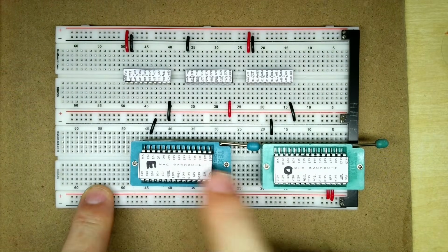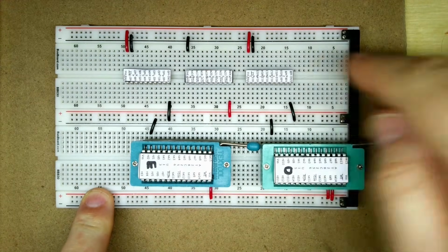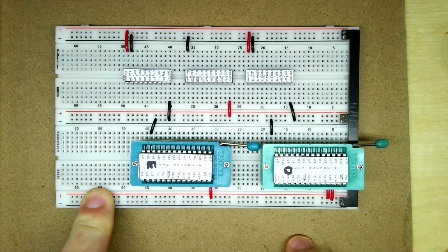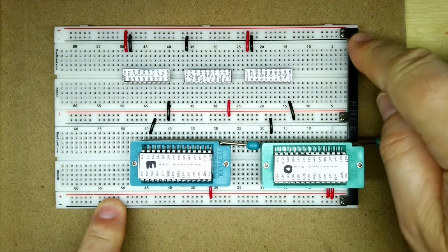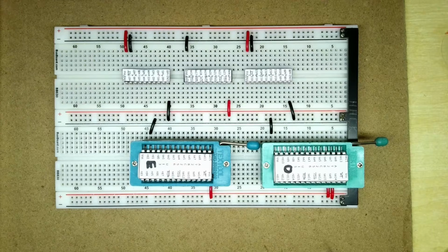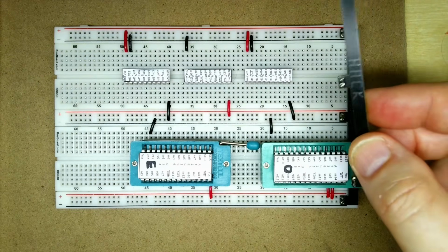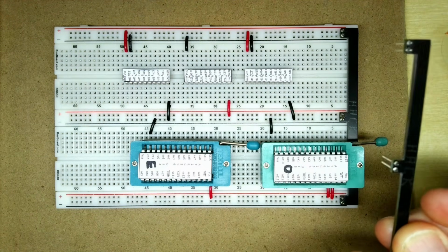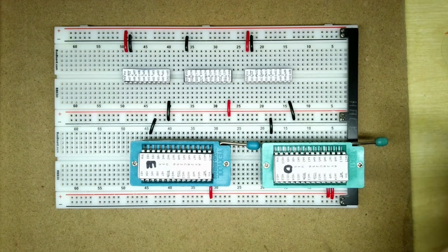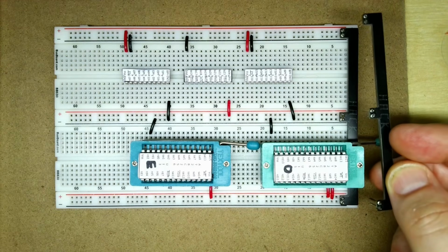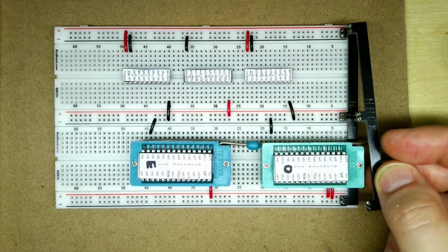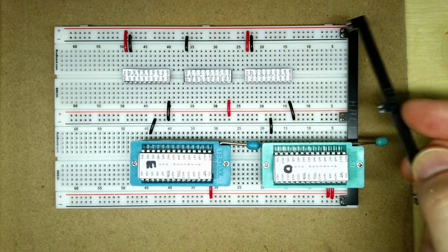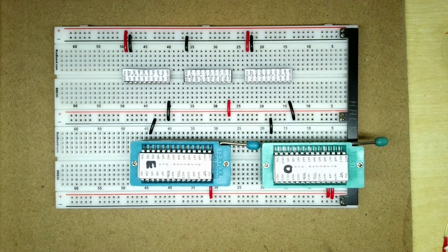So I've stuck the labels on the chips and plugged them in. I did swap the boards around so that the red power lines are on the top, which is consistent with the schematic. This thing over here is a breadboard buddy. These are from Hack Modular on Tindie. They're little printed circuit boards that you can just solder a couple of pins into, and the pins are then connected through the circuit board there. So it gives you quite a low resistance connection between all those things. It's certainly a lot neater than putting wires in there. So that's got all of the power rails tied together there.